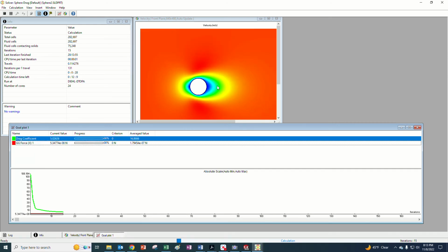A good idea sometimes is to look at the shape of this contour, if you were really looking to improve the thing, where the contour is representing where there's differences in velocity. And where there's differences in velocity, you probably want to make more grid points, or a finer grid, in that region, or at least have points that contain it. You also notice that we have changes that are taking place outside of our domain, and therefore, we might consider extending our domain out further.